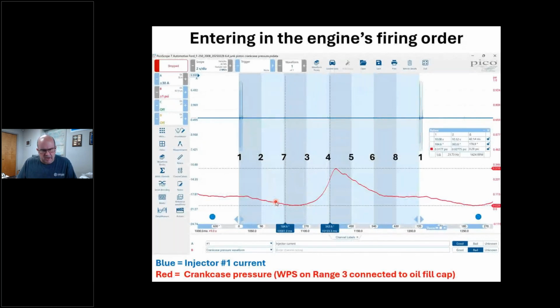Now that's under my spec. Now remember that spec was at 3,000 RPM. The spec was nothing over 10 at 3,000 RPM, but I got 8 inches of pressure in that short amount of time. All right, just run at 12 seconds. That's another no bueno here. Let's see if I can ID what's going on here. Remember, number 4's got our contribution code.